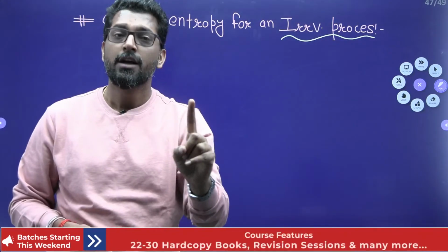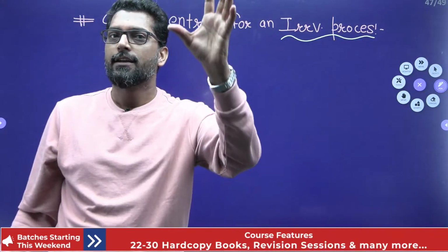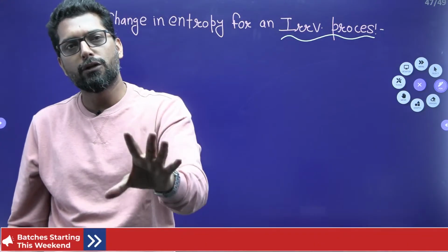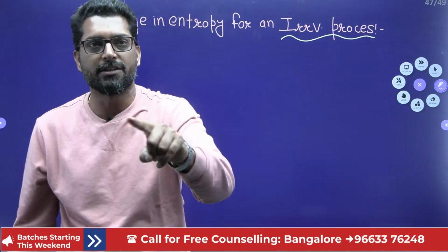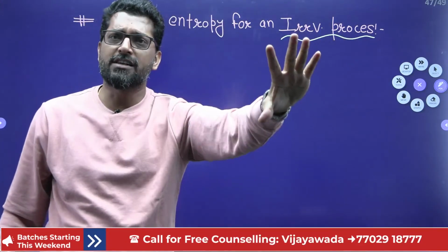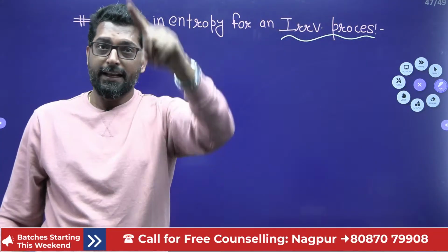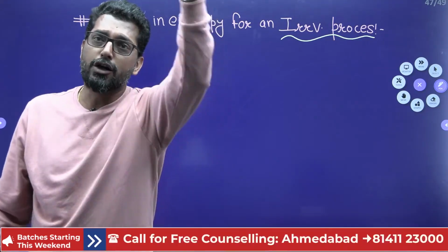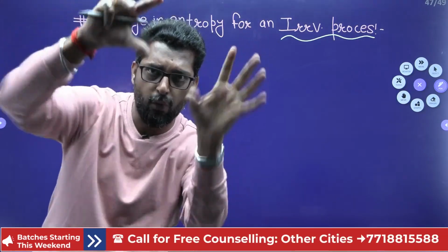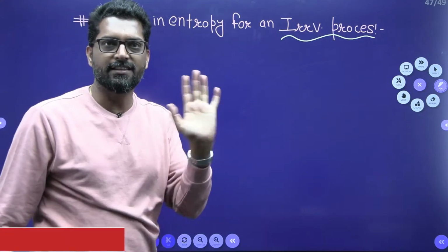What is the common method? You draw a cycle, and that cycle is connected through a process by a reversible path, and that cycle is also connected through a process by an irreversible path. Then you can find it for any process. Anywhere in thermodynamics, if you find the property change for an irreversible process, it's your technique that you can draw a cycle of the same state points with one reversible and the other irreversible, and accordingly you can prove. That is the subtle concept.